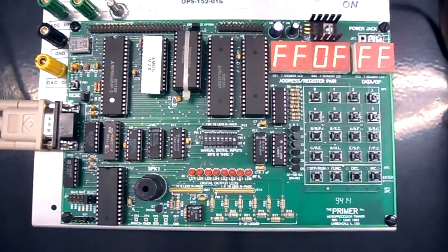So what has happened is, when we press function run, the Monitor Operating System stores the data from the breakpoint, and in this case it was already FF. And then when it hits the breakpoint, it restores the data into the breakpoint, and that data was FF. So we can't have more than one breakpoint set up at a time, or we'll have to manually go in and change it back to what it was supposed to be.